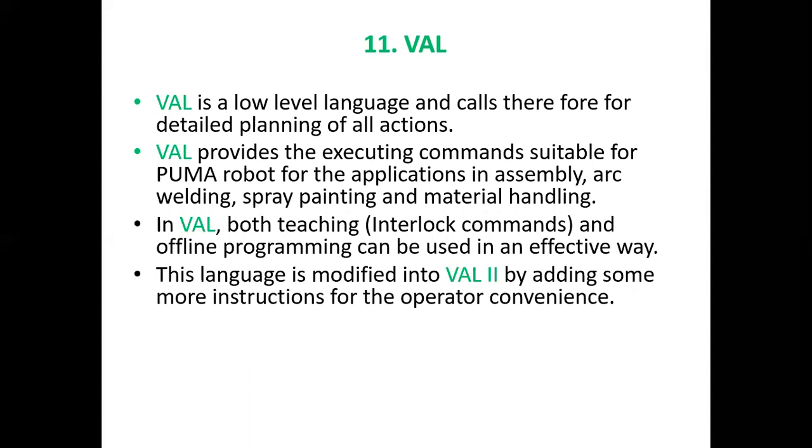So VAL is a low-level language and calls, therefore, for detailed planning of all actions. So VAL provides the executing commands suitable for the PUMA robot for applications in assembly, arc welding, spray painting, and material handling. In VAL, both teaching and offline programming can be used in an effective way. This language is modified into VAL2 by adding some more instructions for the operator's convenience.